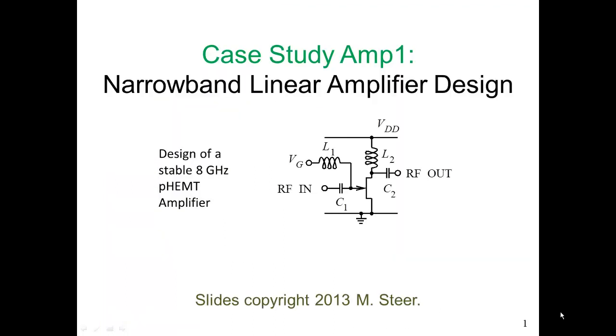In this case study, we will consider linear amplifier design. Linear amplifier design is the basis of all amplifier design. In particular, we will look at the design of an 8 GHz PHEMT amplifier.